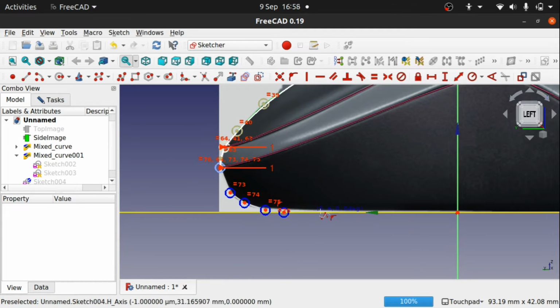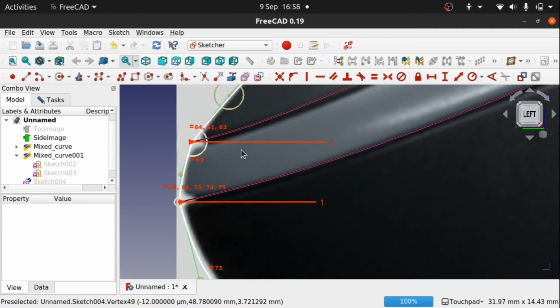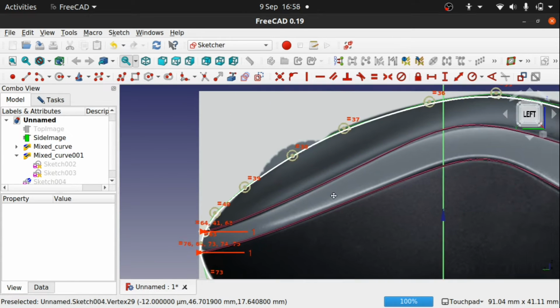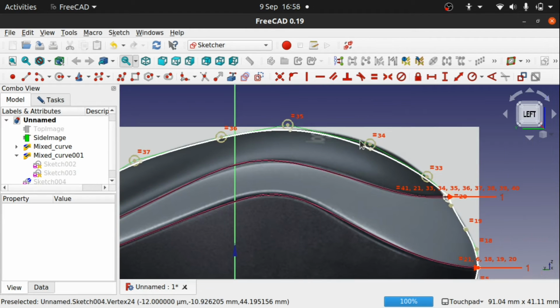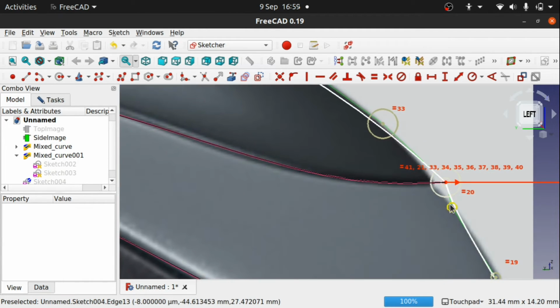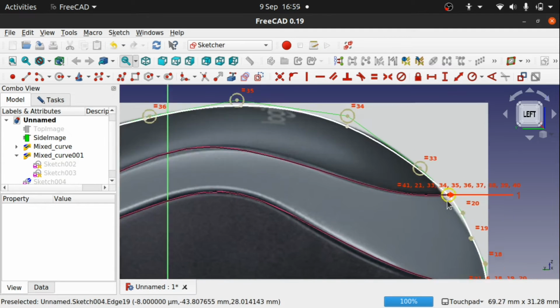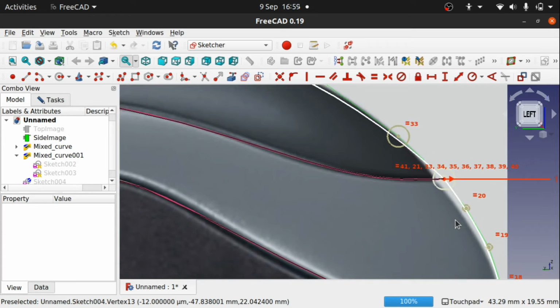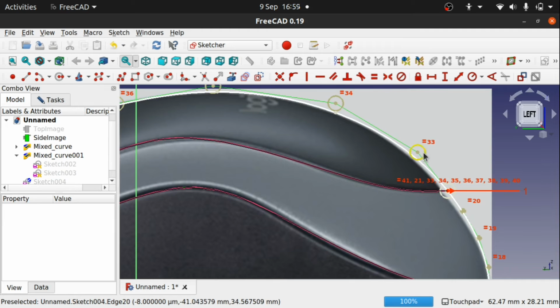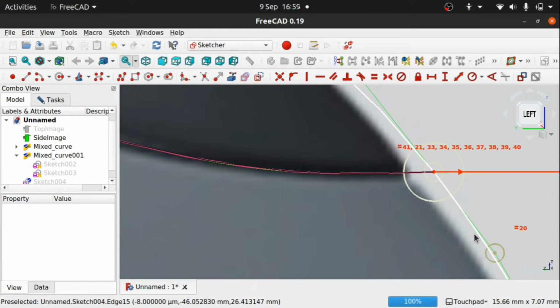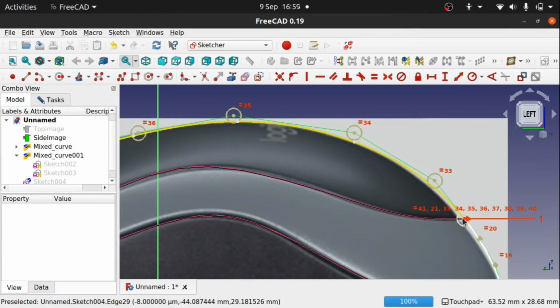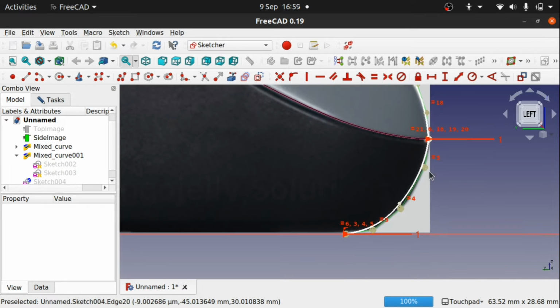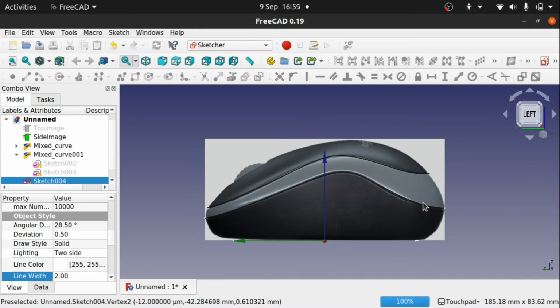And we're going to connect up to that horizontal constraint there. Hit escape again, and we can do some minor adjustments in here to bring these into position. You can see my sketching is a bit out here, so I've just readjusted this to attach to that point and just curve this off. Once we've finished, we can hit escape and let's see what we've got.